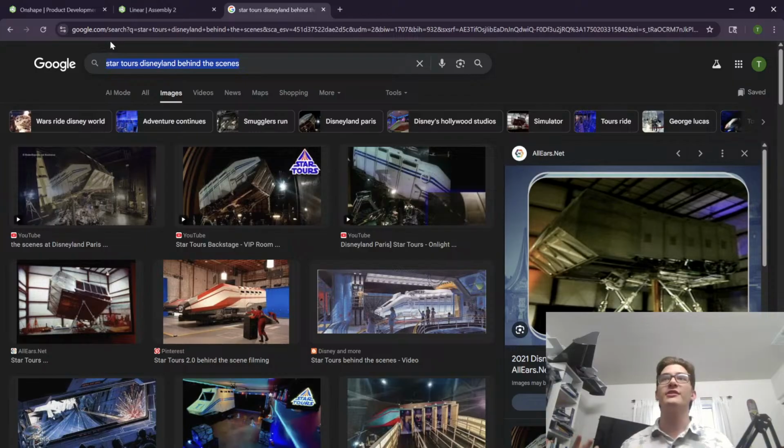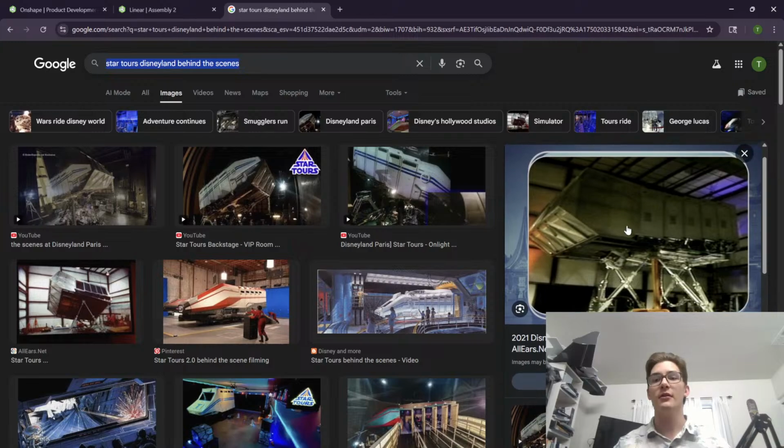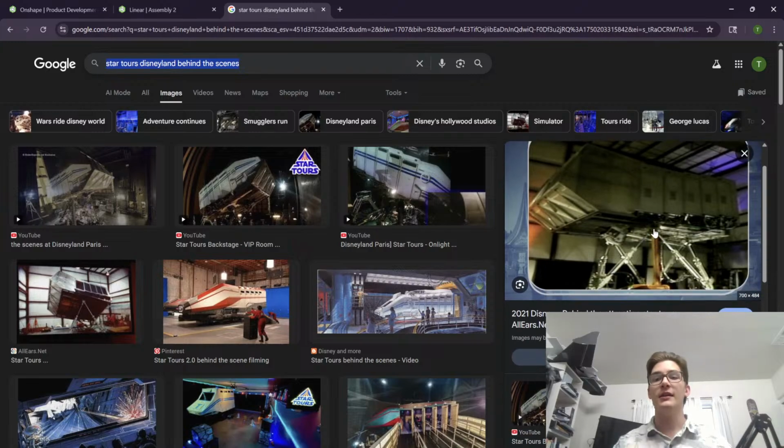But it does over-constrain the system, meaning there's even more ways to drive the actuators in such a way that you break it. Because you can imagine, in this position of the ride vehicle here, if you were just to shorten one of these, that would be an invalid configuration of the actuators. It would be something that would damage the system.